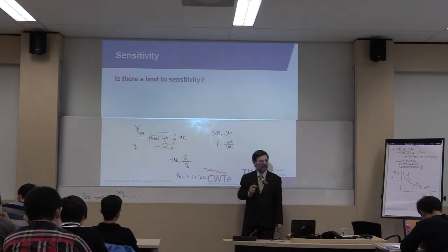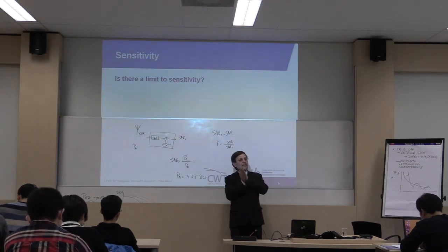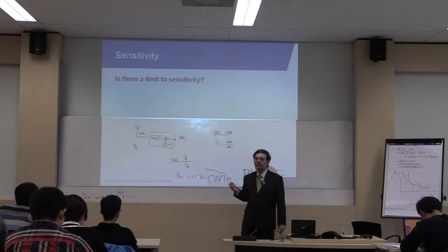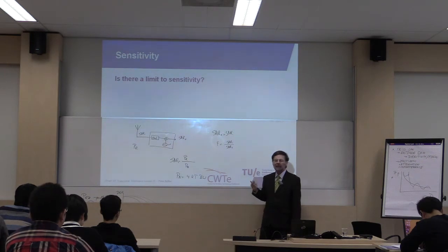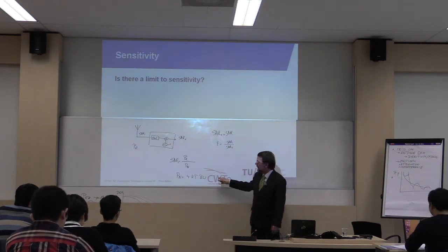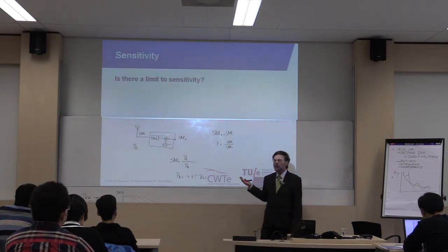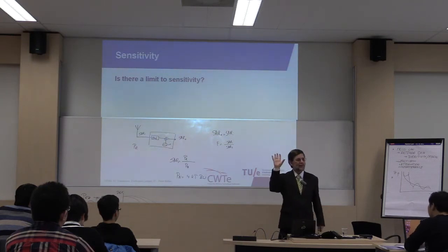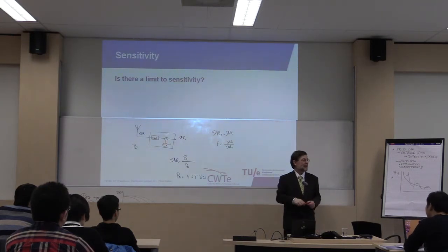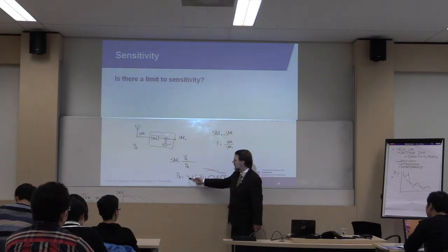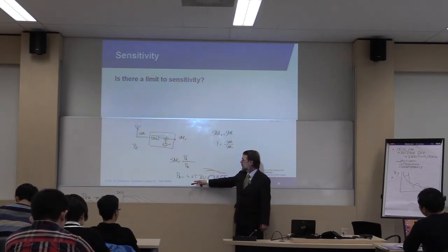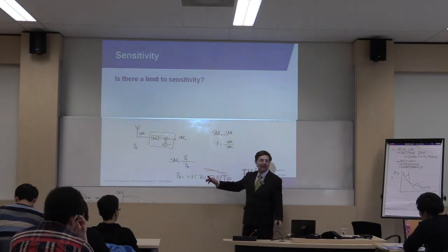So if I have an antenna that has a very narrow beam and I'm looking at the transmitter and that camera over there, then it will be a temperature of about 290 Kelvin, so 20 degrees or so. And in most cases I can work with that number. The case where you need to watch out is radio astronomy, where you're looking towards the stars. It's a lot colder up there, and then you need to work with a lower temperature. But in most designs that we will do, T will be ambient temperature, and then you have 4 times the Boltzmann constant times the absolute temperature times the bandwidth. That's the noise you get.